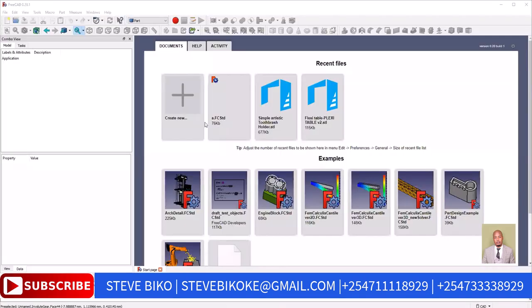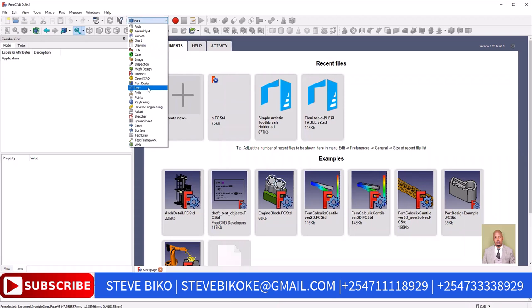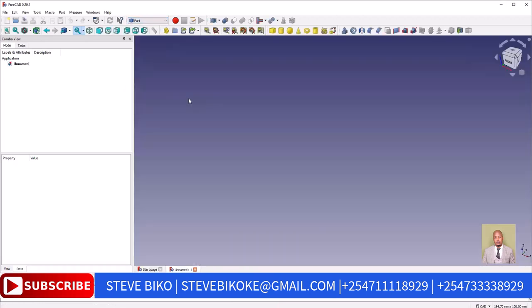Hello guys, we want to make an animation of two gear wheels rotating against each other by using the Assembly 4 Workbench. So we start by ensuring that our design command is at the part. Then we click on a new workspace.